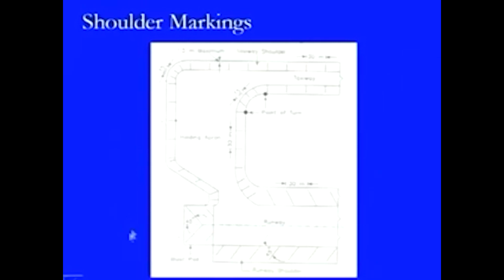This is one diagram which tries to show a runway strip. With respect to this runway strip, on the two edges the markings have been provided at an angle of 45 degrees, and they are located at a distance of 30 meters, but when it comes towards this turning area, then it will be located at a distance of 15 meters. Then here in this location a blast pad is being provided, and this is provided with V-shaped chevrons. That is the way it is being located, and the aircraft will be taking off in this